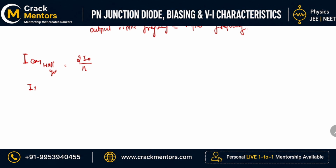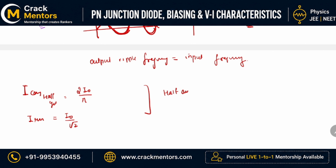Getting it? What is the value of the RMS current for a half cycle? The value of the RMS current of the half cycle is equal to I naught by root 2. Since I am having only the half amount over here, I will say that the value of the output current, you can say from here,